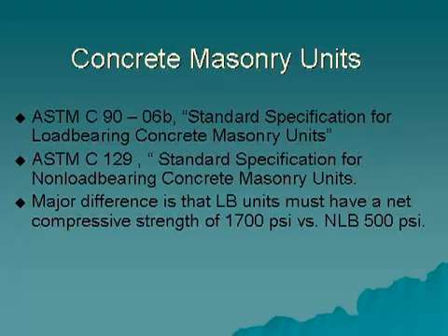Also, it's worth noting that most block manufacturers do not inventory non-load-bearing concrete masonry units, as this would be a special request item. Check with your block manufacturer for availability of these types of units.